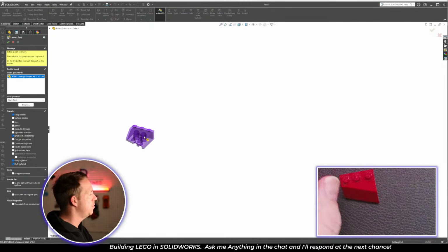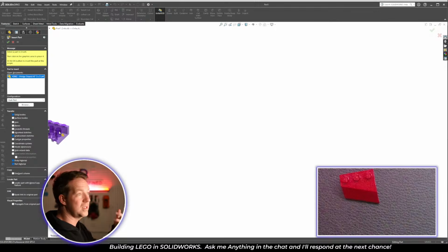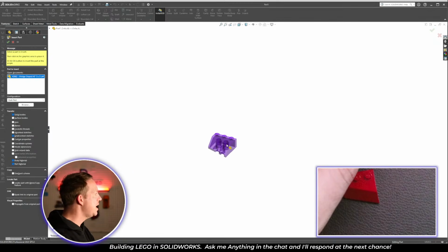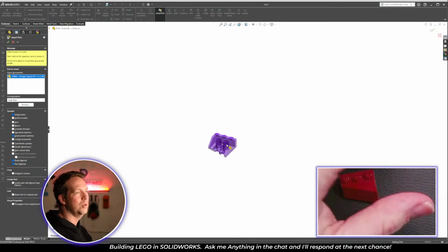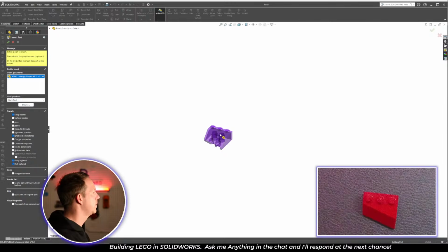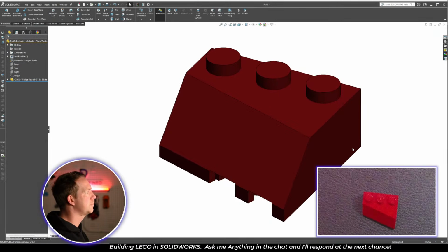When you do this insert part tool, you can have the option to include things like surface bodies or planes or axes or sketches, or materials. And you can actually locate the part, so you can put it in a specific location like you would mates in an assembly. I don't need any of that. I'm going to skip it all. I'm just going to bring in the visual properties and press OK.